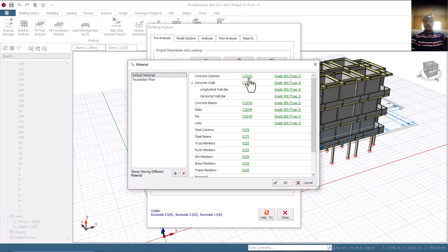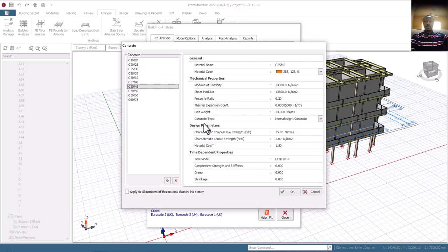All right. So for the superstructure, the grade of my concrete, I'll come here. This is showing grade 35. So let's click on this to confirm that. Can you see characteristic compressive strength fck? Why we are saying fck is because I'm using Eurocode. So you can now see 35. This is a small structure. I cannot be using 35 for this kind of structure, so I'm going to use 20. I'll click on this to confirm that I'm using grade 20.